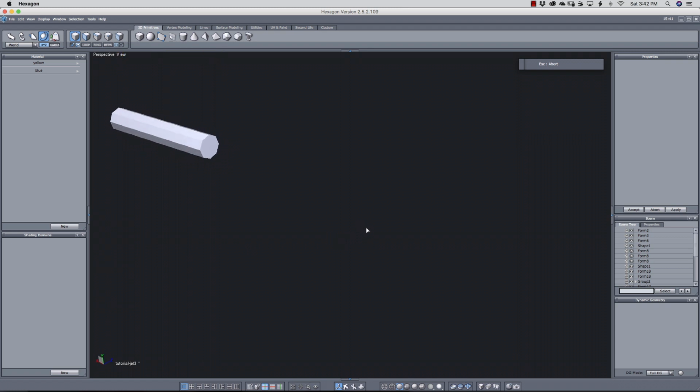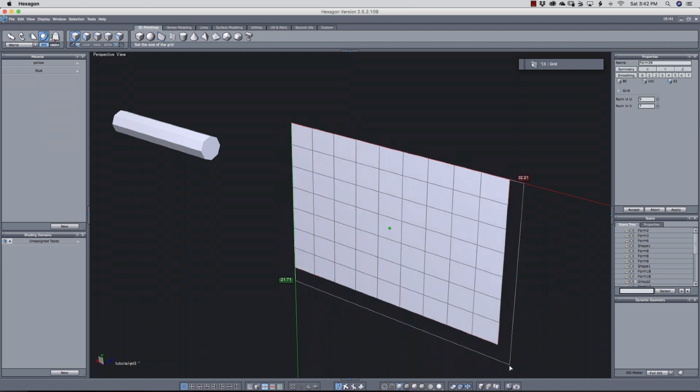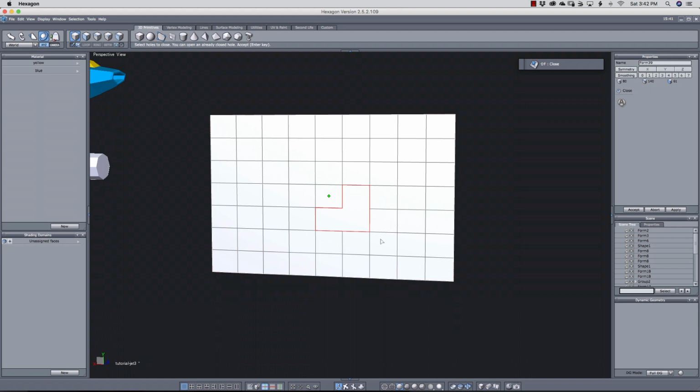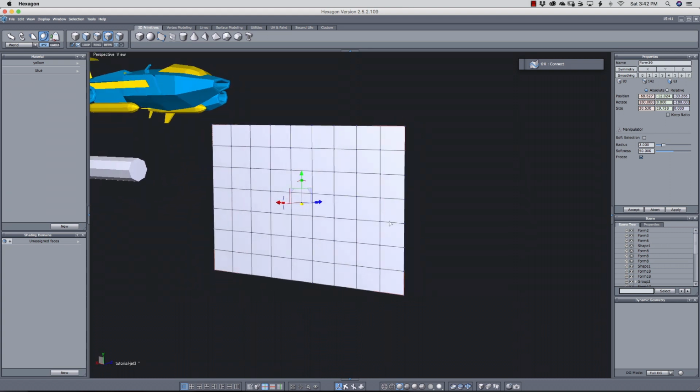Here, I can make a quick grid shape pressing Alt 5, set the initial size, then draw out the grid, and then I can select these and make a hole, delete these polygons, and I can fill the opening with the Close Hole tool, Shift F. And the important thing to note here is that yes, it fills the shape with the polygon, but typically it's going to create an n-gon, and I'll need to remedy that by reconnecting vertices, like this.